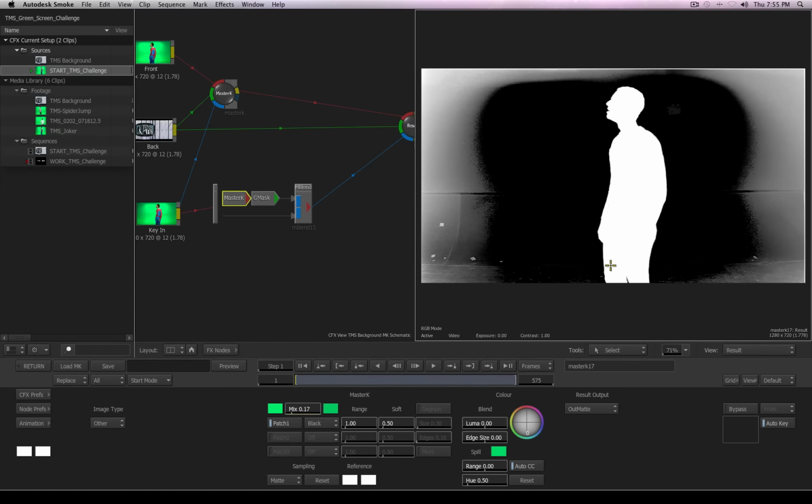select my garbage mask tool right here. We click in this side, so we're activating this viewport. This allows me to access the Add tool. I'll click Add, and I'll just click and create a couple control points around the guy, something like this.